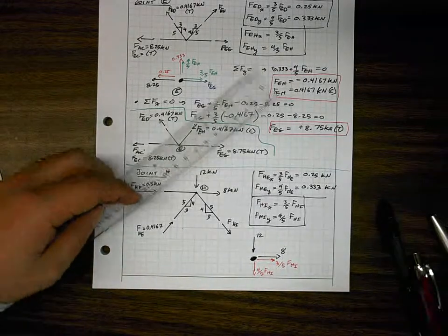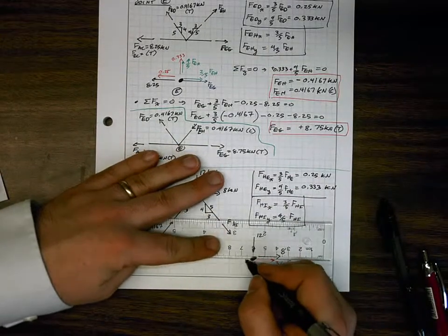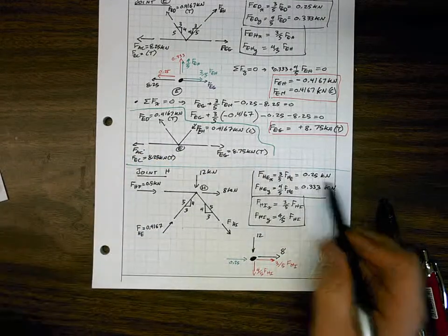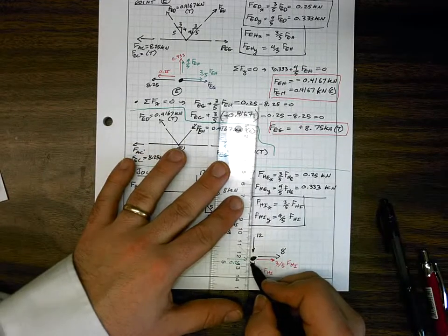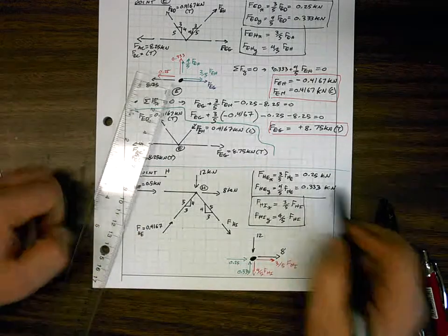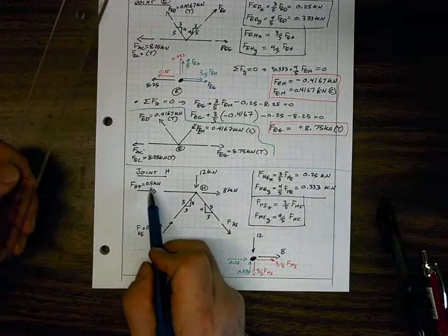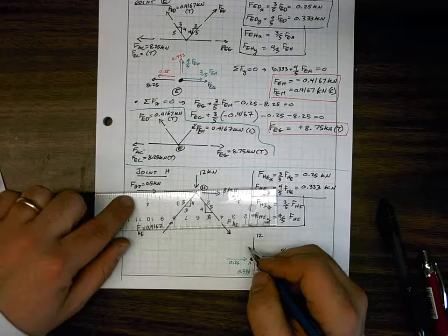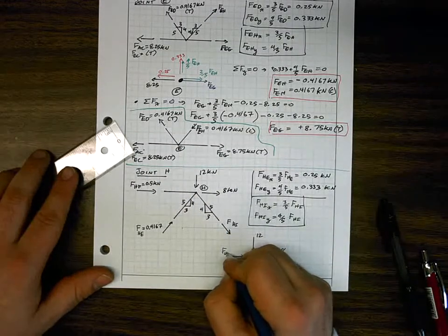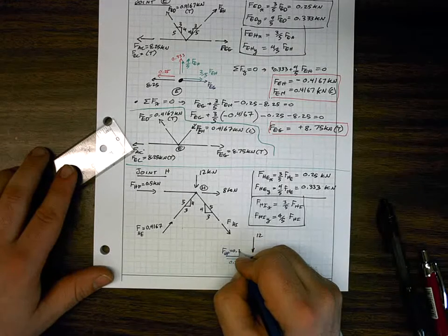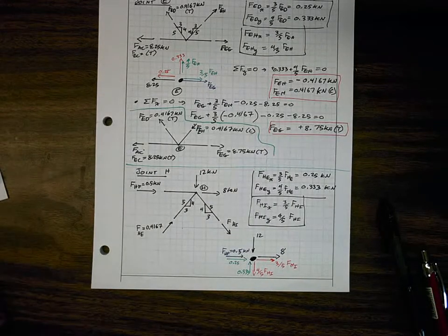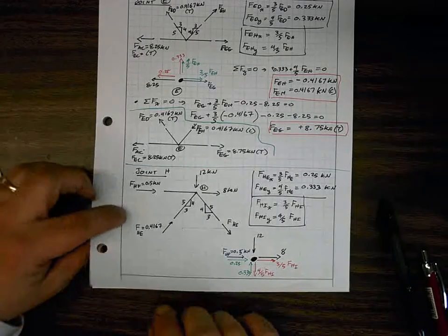And then we've also got forces acting at this joint, 0.25. That's this value, FHEX, and a value here of 0.333. That's that value, FHEY. And finally, we've got force FHF framing into that joint. FHF is equal to 0.5 kilonewtons. So that's our free body diagram for the joint in our Cartesian coordinate system, our global coordinates.